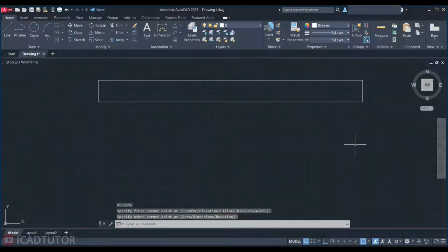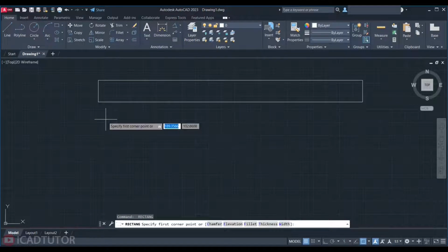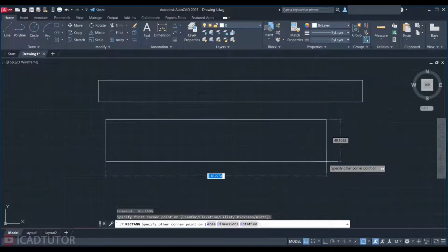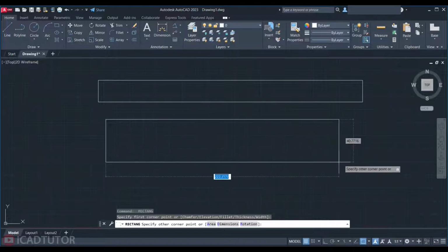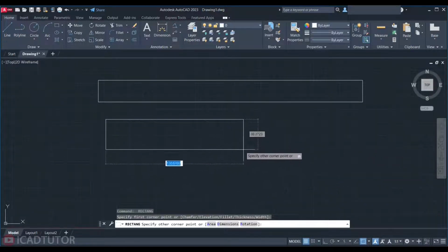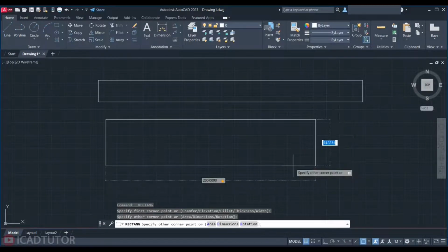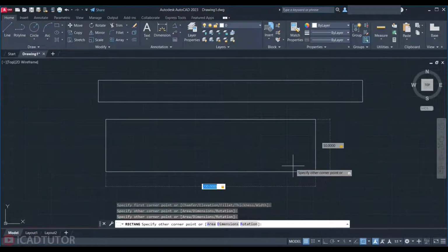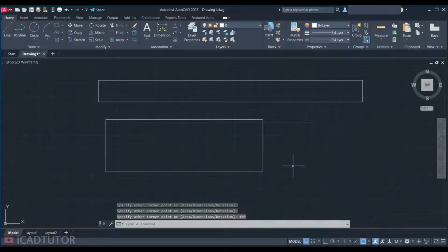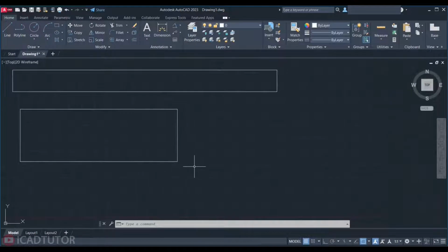If that's not what you want, and if you want to specify the length and the width of the rectangle, it's very easy. It's like the line tool. And the dynamic input is active. The blue box says enter the length, 200. I want to enter the width, press tab, 50. Oh no, the length size is wrong. No problem, press tab and enter again. 150, enter. Guys, as I already said, if you remember, we can use the tab key when the dynamic input is enabled.